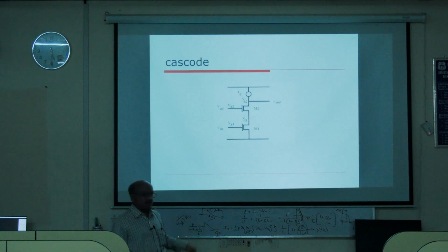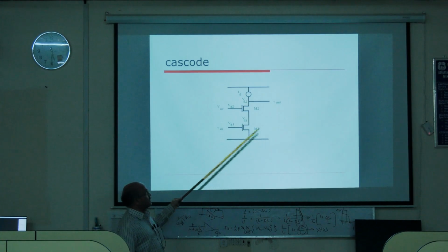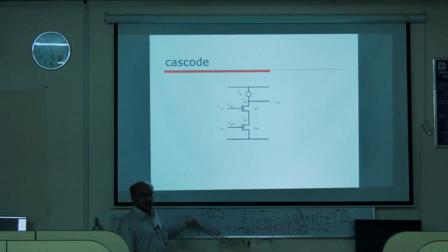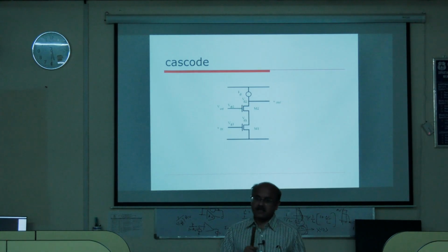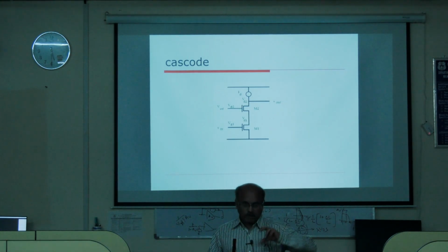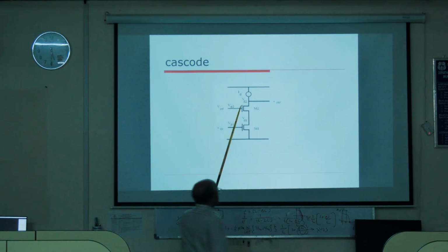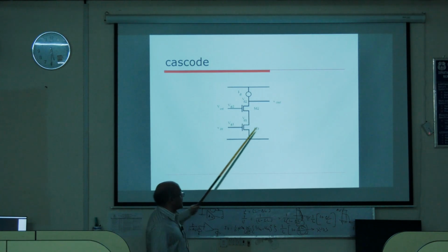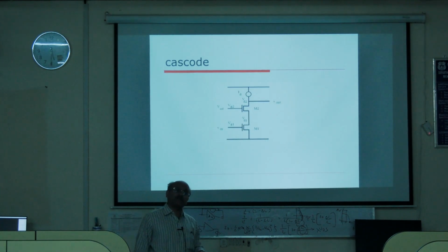When that is happening, and the change is in such a way that this voltage is increasing, then VGS2 is decreasing. As VGS2 decreases, the current is decreasing. So it is not obeying us in total. To some extent, according to the applied gate voltage the current is changing, but this current change now is not just a function of this Vin, rather you can find that there is some slight reduction in the current by virtue of the variation of this voltage. This is a sort of feedback that you can think of.